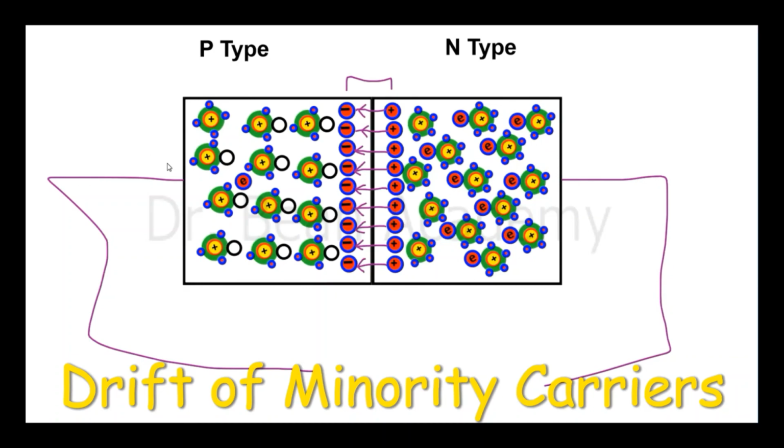You haven't connected anything with the PN junction diode, and I told you that there might be some free electrons in the p-type region, although it's rare and they will be in very small quantity. The majority of the charges are holes, as you can see, so there might be some free electrons on the p side as well. Just consider them as some type of manufacturing defect. There might also be the breakage of some covalent bonds.